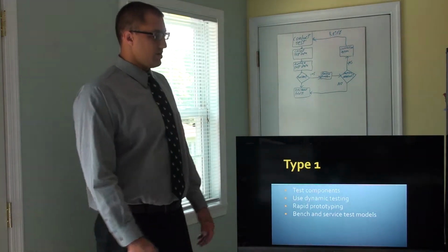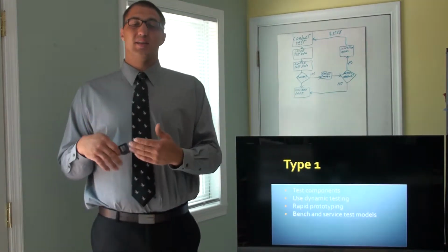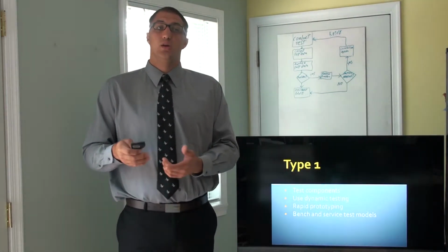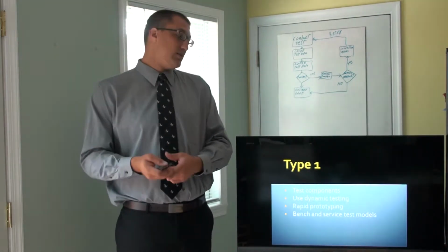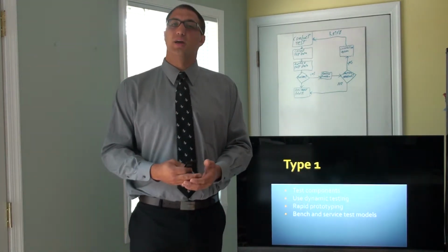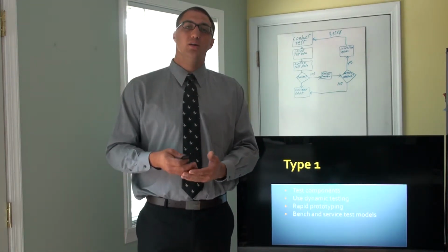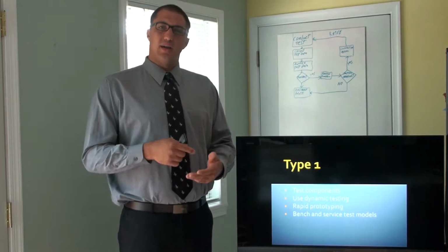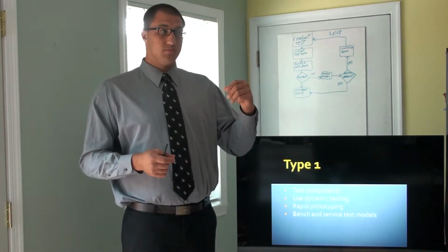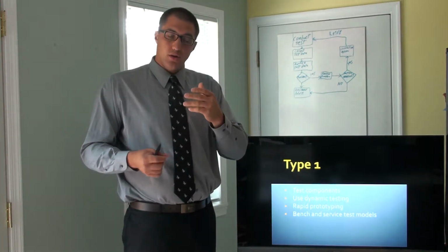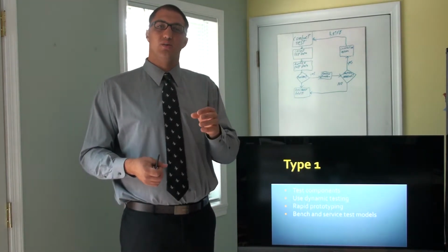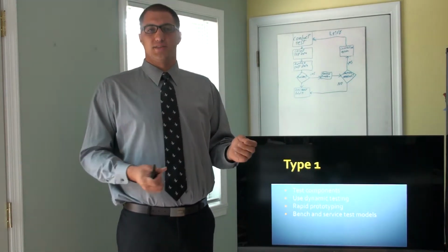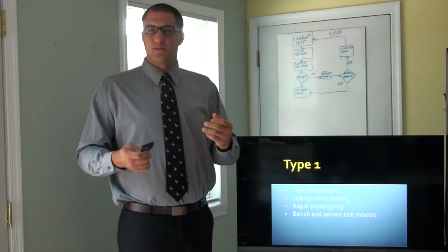Type 1, you're going to be testing components. You're going to do dynamic testing, bench testing, like breadboards, using oscilloscopes, using load testers to test strengths of materials. You're also going to do rapid prototyping, like three-dimensional printing. If you don't understand three-dimensional printing, basically it's a X, Y, and Z axis CNC machine, and instead of taking away material, you're producing material through an orifice at the top. Usually it's a low melting point plastic or a catalyst reactive plastic.